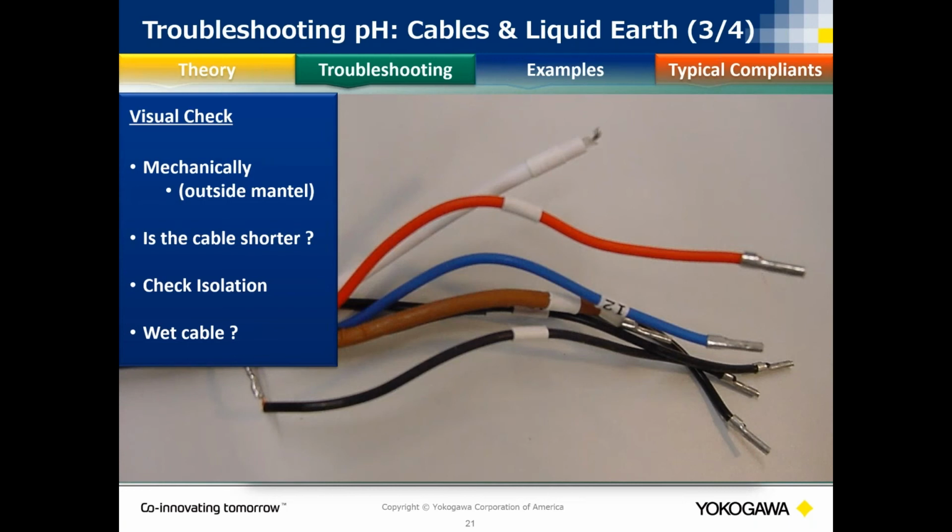This one, take a look at this photo. I've got two things here that we've seen with this cable when it was sent back to me from a customer because it wasn't working. The top one I want you to look at is the top white. You can't really see it. Basically, all they did was cut off the terminal pin and then shorten it back and strip it back. That one's not necessarily going to cause as big of an issue. But look at the black cable at the bottom. They basically shortened it, somehow stripped it, and then put a soldering iron to it to kind of seal it back into place. That right there is going to cause a big